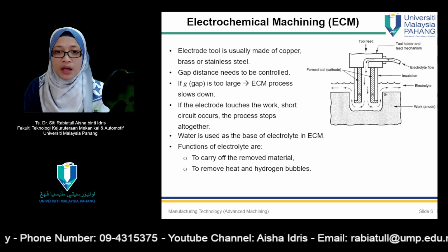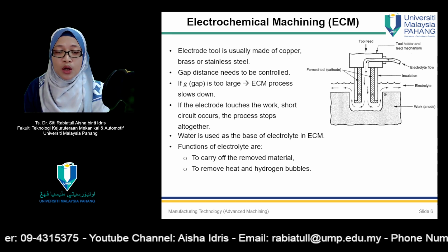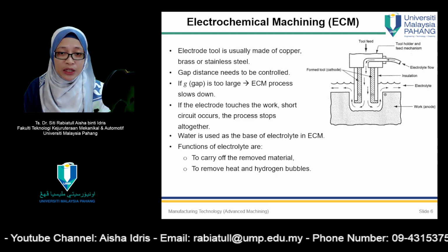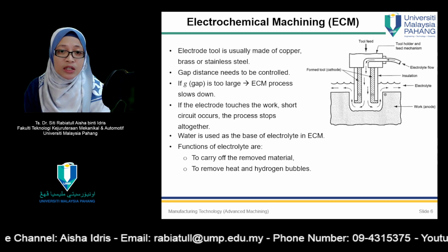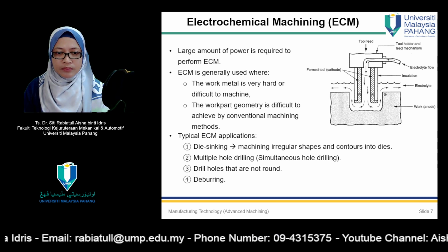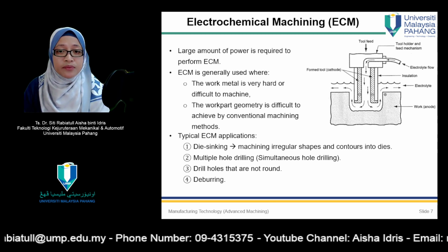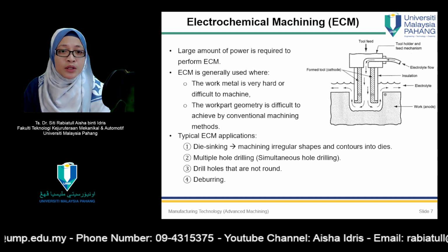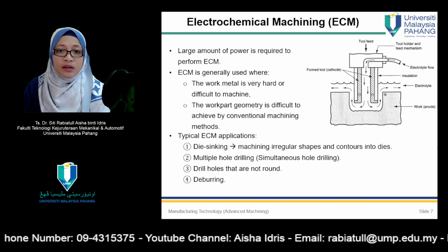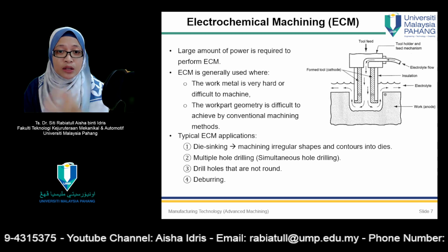removal from the work. Metal removal rate is determined by Faraday's first law, which states that the amount of chemical change produced by an electric current is proportional to the quantity of electricity passed. Water is used as the base for electrolyte in ECM to reduce electrolyte resistivity. Salts such as sodium chloride or sodium nitrate are added in solution.